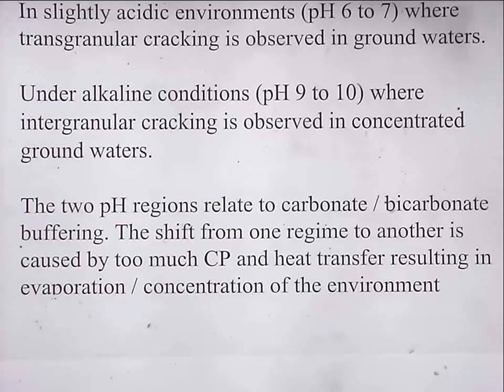Now you might merely say, oh well, if the pipes are being cathodically protected, then how do you get anodic stress corrosion cracking? And the answer is that in the bottom of a capillary, you might have a negative potential out here on the bulk surface, but at the bottom of a capillary the potential can be entirely different. It could be positive, because this thin area of solution in here has a high resistance, and you don't get good potential control from your bulk CP system down a crack. It just doesn't happen.